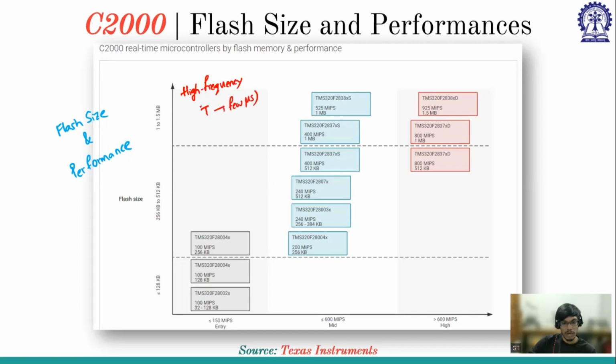So our microcontroller has to generate the reference within a few microseconds, which means it has to compute all these instructions at very high speed. So accordingly, we have to choose. If we choose a very low performance microcontroller, then it itself will take more number of cycles than the converter itself. So it is not compatible for that application.